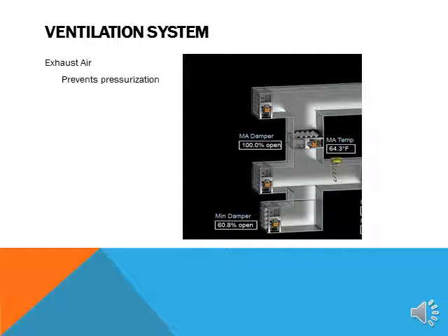Most of these supply and return systems have what we call a lead-lag, meaning the supply air runs at a certain speed to maintain air, and the return air runs at a little bit less speed, thereby allowing for kitchen exhaust, bathroom exhaust, or other items that need to be exhausted from the building to be released from the building without affecting the static pressure of the building. So at the end, air needs to come in the building and be exhausted out of the building evenly to maintain the static of the building, so it's not in a positive pressure or a negative pressure.